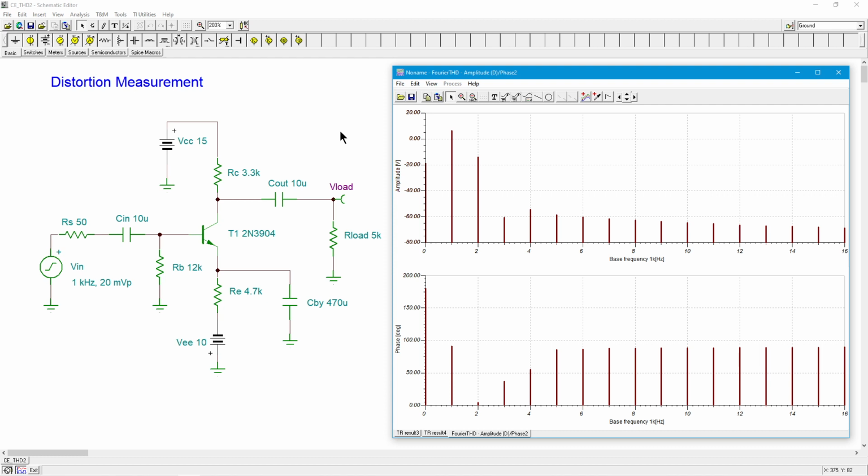Okay, beautiful. So now we know how to do distortion measurements in TINA. That's fairly useful, right? So when you're talking about just using your eye, yeah, you can tell someone's got 5 or 10% THD. But if you're talking about 0.05 versus 0.1%, not so much. You're going to need to do a proper analysis, right? So remember, just go through the Fourier and you can see the total. And then if you really want to break it out, you can use the draw option on there.